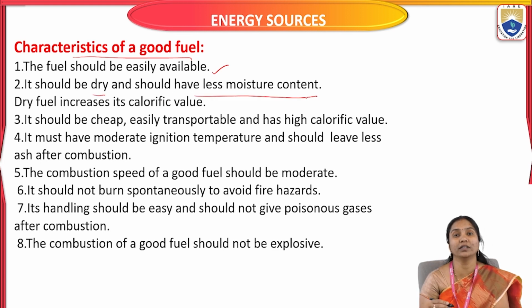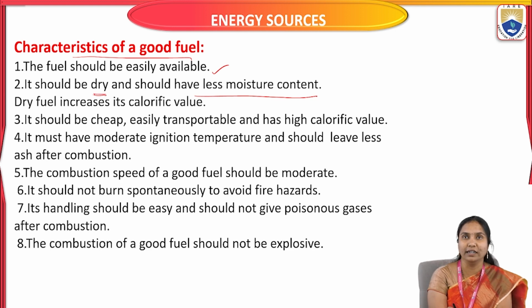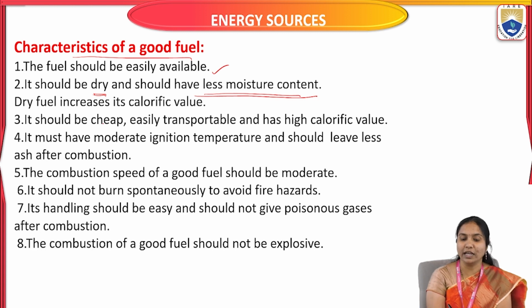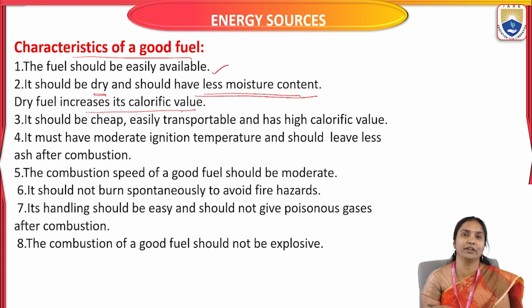Good fuel always contains low moisture content. If this percentage is high, the calorific value decreases, because it requires more heat for burning. So a good fuel requires a low percentage of moisture content. It should be dry and have less moisture content. Dry fuel increases its calorific value.